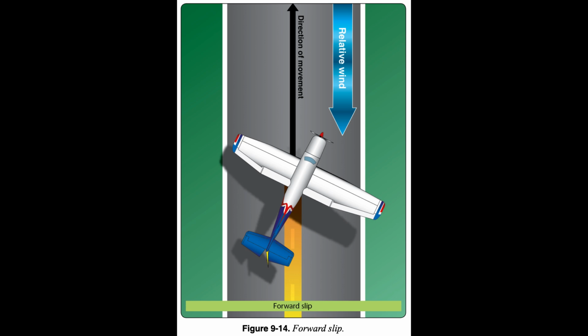been reached, lowering the nose not only increases the sink rate but also increases airspeed. The increase in airspeed increases rudder effectiveness, permitting a steeper slip. Conversely, when the nose is raised, rudder effectiveness decreases and the bank angle should be reduced.